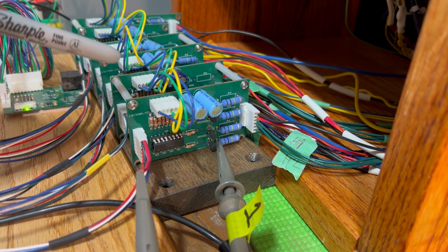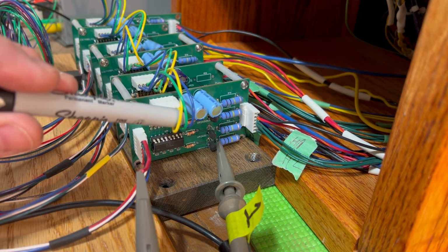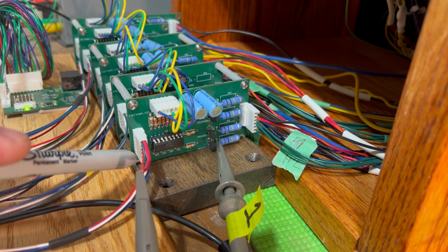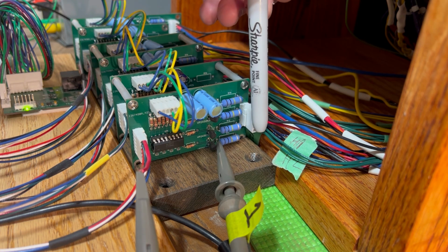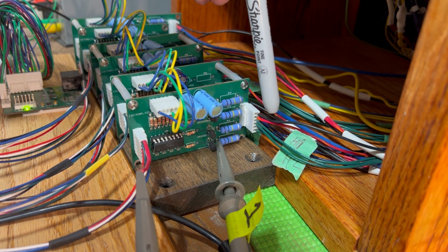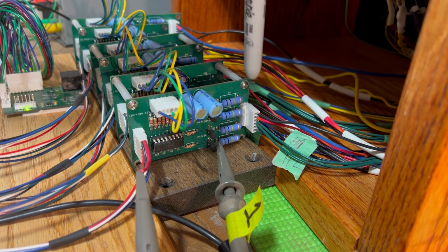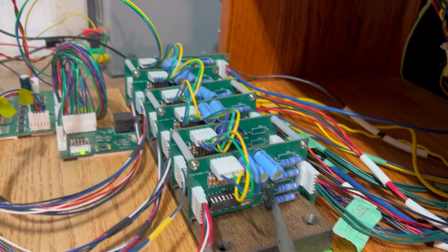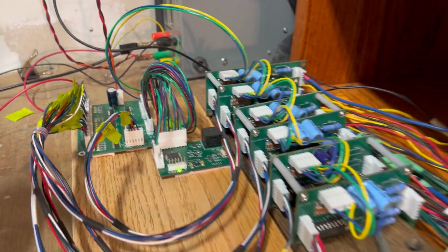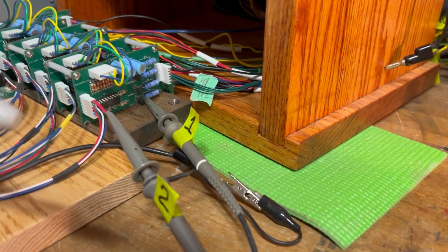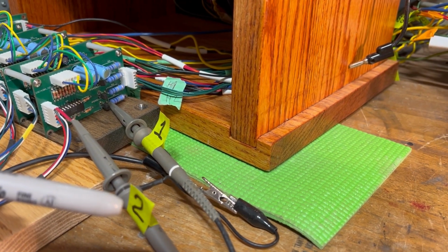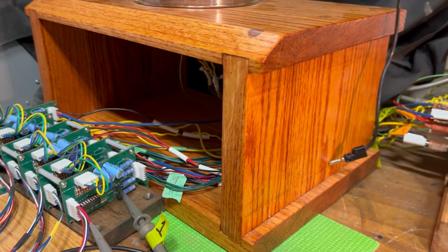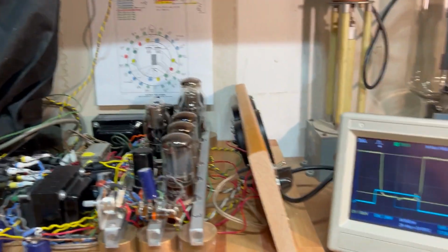So returning to the front here, this is the plus minus 12 volts for the transistor side of the opto isolator. Here's our digital input, our output going to the selector bars. I also have my minus 250 volts here, so I'm trying to be careful not to touch this thing. So I have my microprocessor stepping through what it was doing for the introductory sequence. And all I'm going to do is just show you some timing signals right here. Channel 2 is the digital input. Channel 1 will be the selector bar voltage. And we're going to come around to the oscilloscope and have a look at these signals.